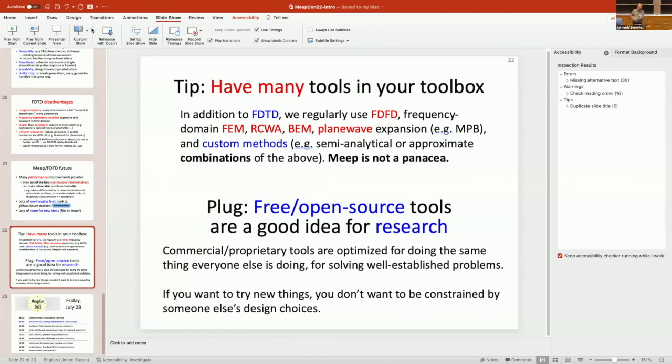So if you put in Meep with periodic boundary conditions and you look for the resonant modes, then it should match MPB to high precision. That's a good way to check, and that's how we checked the convergence rate and the accuracy of subpixel smoothing: we could take MPB and crank it to really, really high resolution to get a really accurate solution, and then we'd see how fast Meep converged to that.